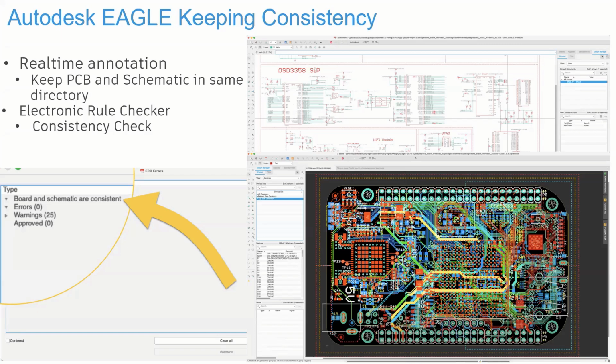So once you create your electronic document, now here's the key. You need to create that electronic document first, then you're going to go ahead and reference the board, reference the schematic, and run your ERC to make sure that you have that consistency. And it actually does work. I have not worked with any design myself, or if users have provided us their designs for support purposes, that I've lost consistency so far. So once I load them, I've been working so far. So it works really well.